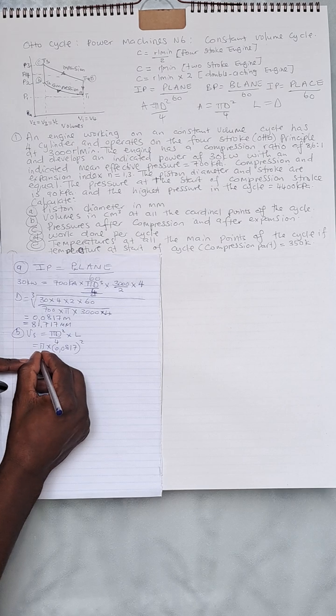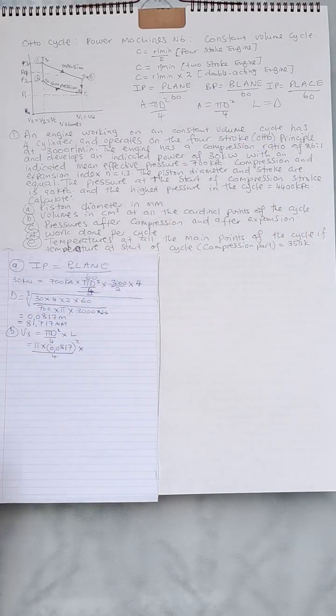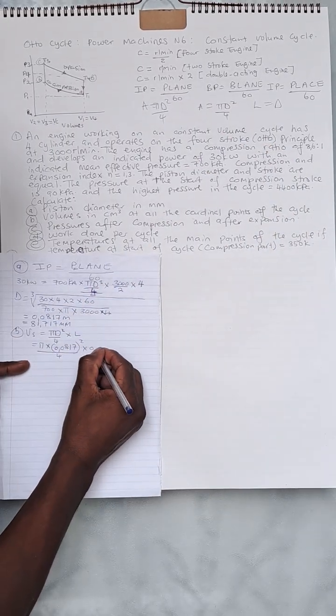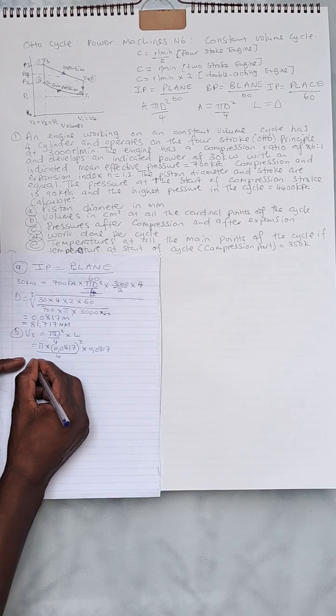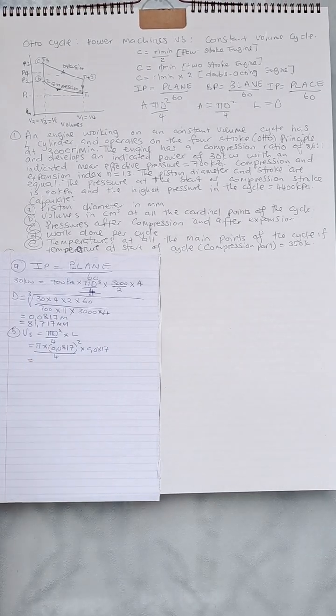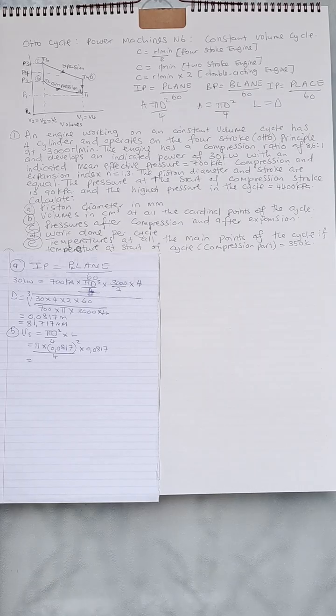Don't forget to square it over 4 times our L. Our L was equal to our D, so times 0.0817. So let's get our swept volume. Perfect, which is I'm getting